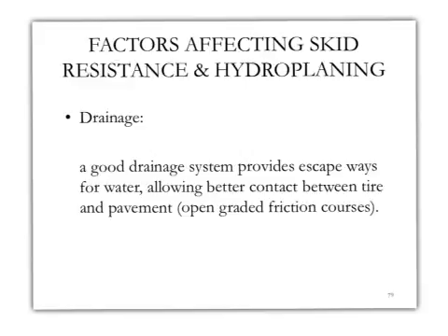One of the aspects that we also need to think of as a preventive methodology to prevent the road from losing its skid resistance is drainage. We got to know this in the previous chapter, that drainage may affect the entire structure, from the structural performance, if the water can get into the system, and we're gonna lose support from the soil and the base and sub-base materials.